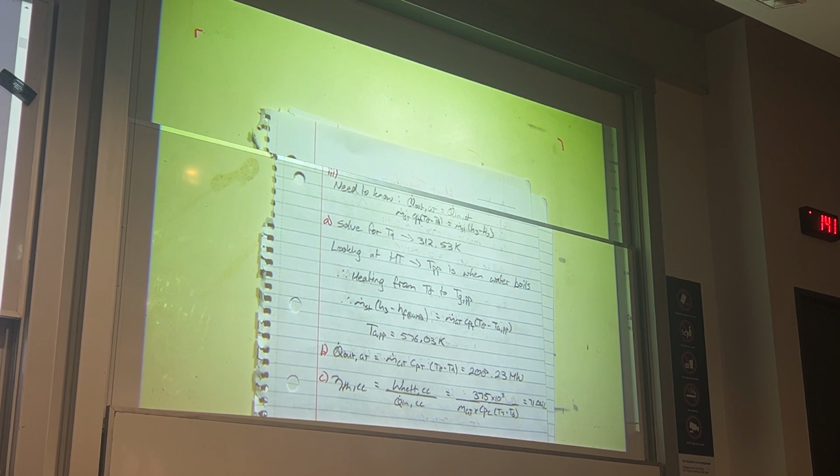because that's not related. But as I was saying, this plot's sort of deceiving because it's just temperature and heat transfer. So as you could imagine, as our exhaust gas decreases in temperature, our water must increase in temperature. But I think it's easier to understand intuitively if it were to go with time. So as our exhaust gas comes down, and you can see it here, even though it's not to scale really, the pinch point occurs when we begin to boil our water.